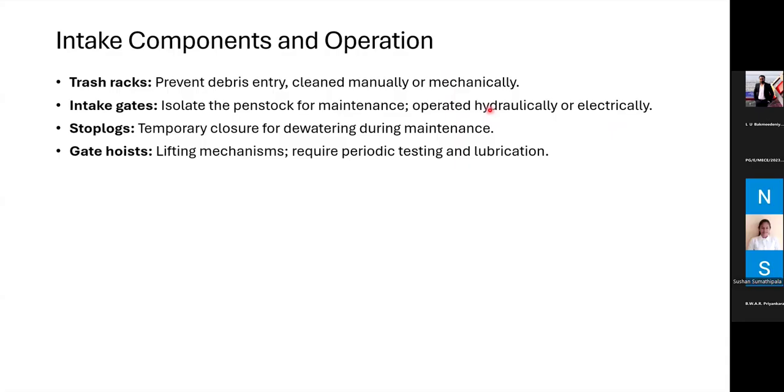Stop logs provide temporary closure for dewatering during maintenance, and gate hoist lifting mechanisms require periodic testing and lubrication. So as we see here in the intake, we have mechanisms for temporary closure for dewatering and isolating the penstocks.